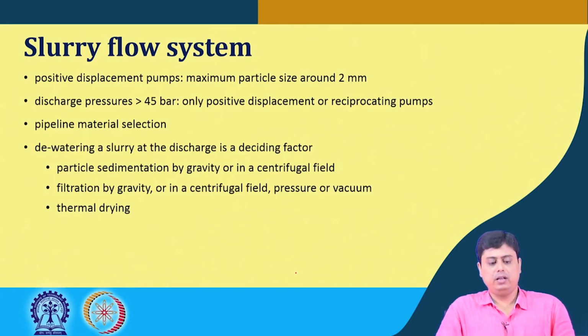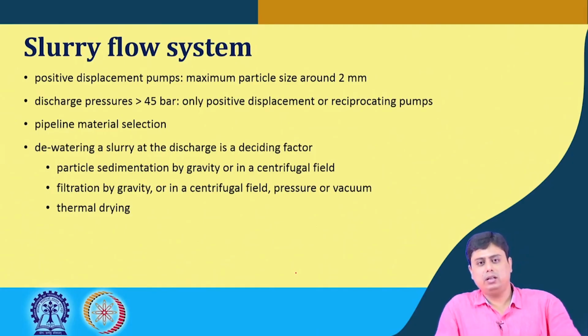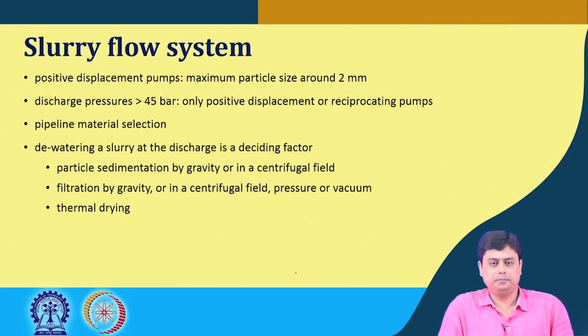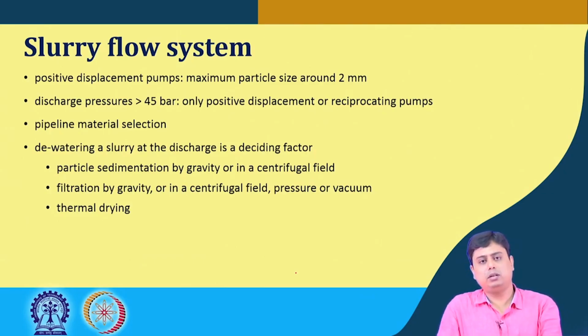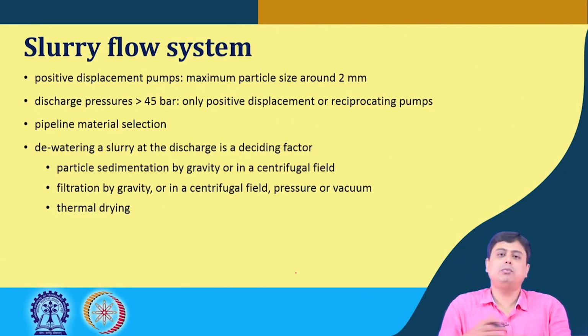And dewatering of slurry at the discharge is the deciding factor whether such slurry transport is effective or not, because eventually if you cannot dewater, then this whole matter of slurry transport shouldn't be there. So, this is the most important parameter that you have to think about beforehand before you transport your solid particles in terms of slurry.